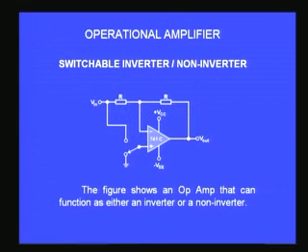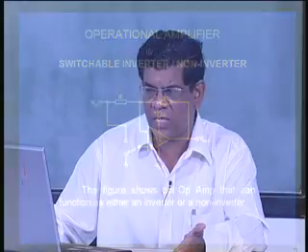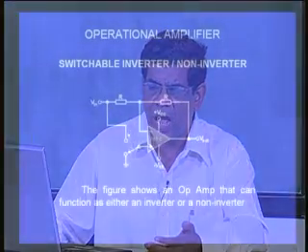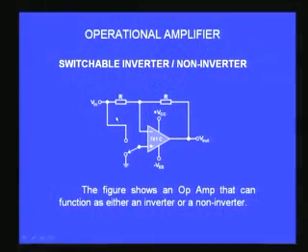After learning the earlier circuit using the superposition theorem, you can immediately recognize that I can now have an amplifier which can switch between an inverting amplifier and a non-inverting amplifier. If I want an inverting amplifier, it is very simple. For example, I have replaced one of the wires that you saw in the previous circuit with a switch here. It is called a single pole double throw key. Therefore you can either connect this terminal 3 to ground, or you can connect it to the input Vin.